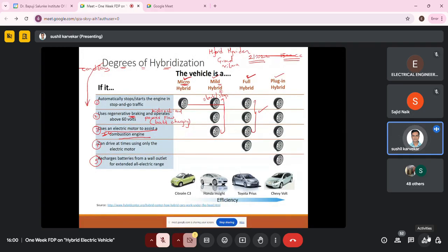As I said, the tractive force is the power which we want in order to move the vehicle forward. For moving the vehicle forward, we require a certain set of conditions. First of all, I have pre-decided that I want to operate the vehicle at 40 kilometers per hour or something like that. So that is one such input. For that, some force needs to be calculated. Let us call that force value F1. This is the force or energy which can be quantified for generating a speed of, let's say, 40. This is only an example.